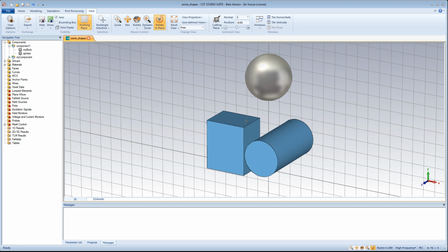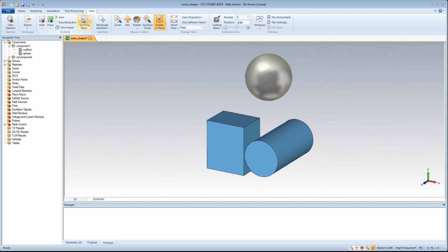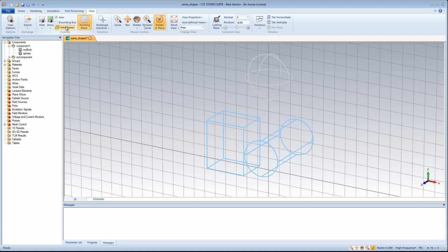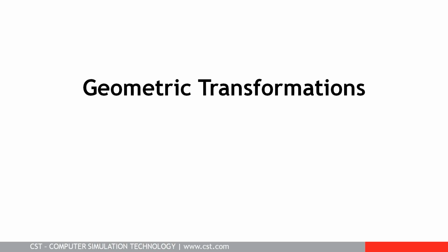By default, the origin for this operation is located at the current mouse pointer location. Optionally, pressing the Control key while using the mouse wheel performs a zoom operation around the center of the screen. In addition to these options, some specific settings are available to change the visualization of the model. You may toggle the visibility of the coordinate axis and the working plane. This setting chooses whether all shapes are displayed as simple wire models or as solid objects.